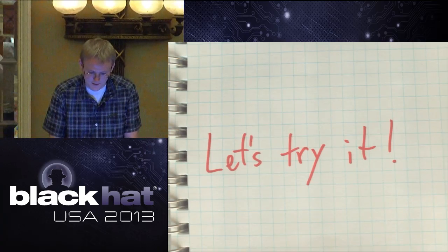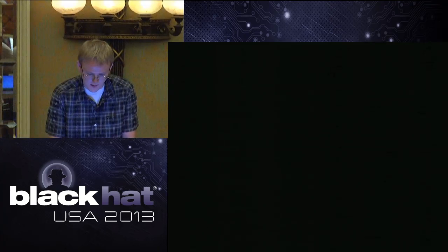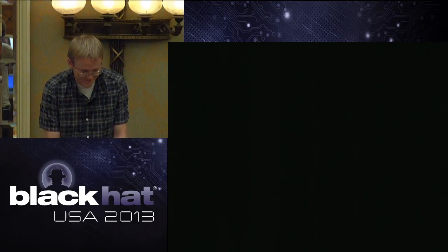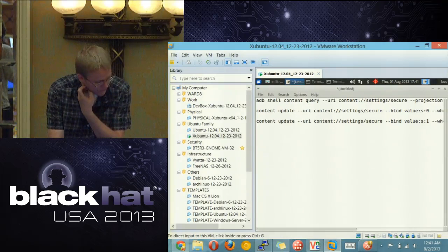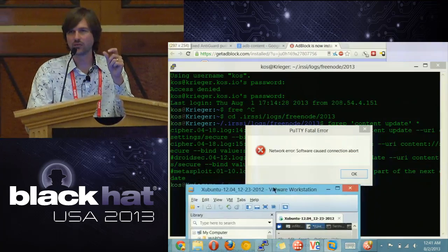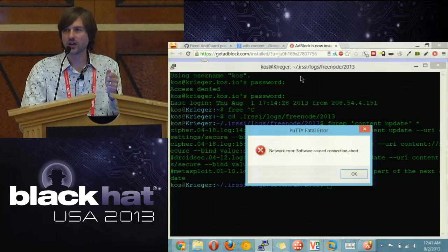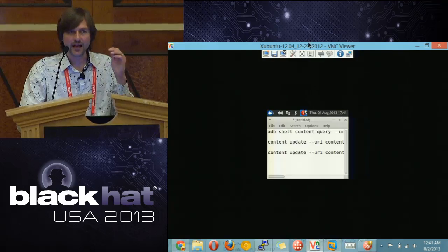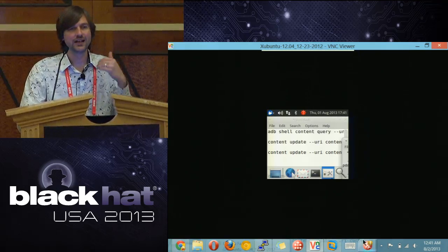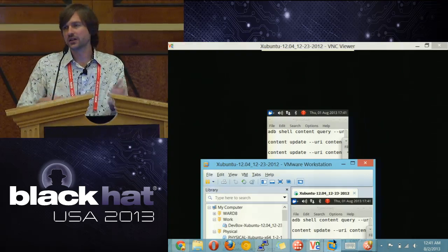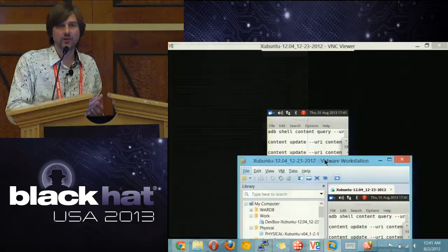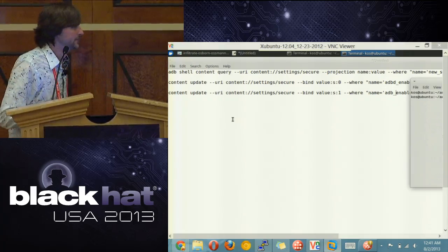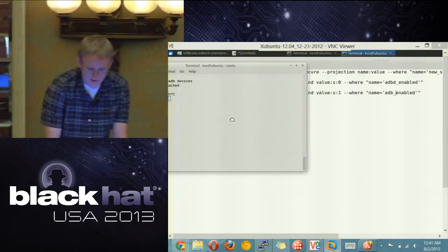Okay. We're going to switch it back over. If this crashes and burns, I apologize heavily. So the goal here is to use our little home-built FTDI port with the connector, connect to the target device, and get a shell using that IQ debugger. From that shell, which is unprivileged, enable ADB, then unplug the serial connection, plug back in with a regular USB connection, and use ADB to take over the device. All right, so I'm hoping this is going to work.